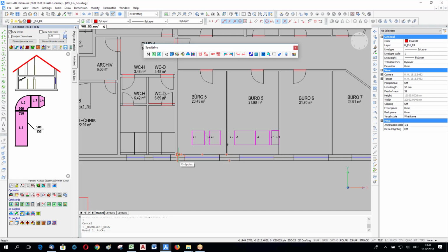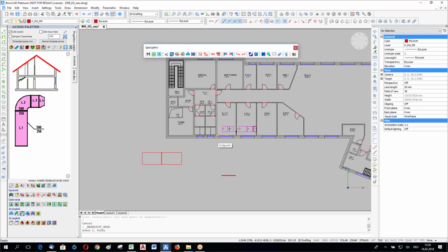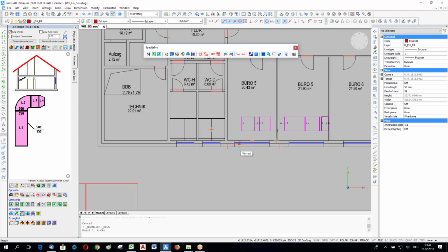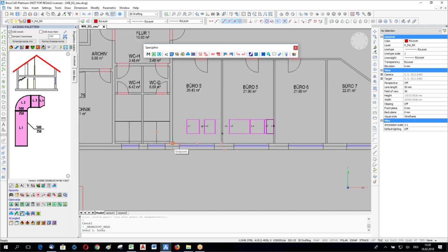The second piece of information is that the software will ask you where the section should be, or where you want to draw the section. I want to have it here in this architect's element, and the first point I selected in the plan view should be on the same position as you select in the section in the second step. So as an example, the first point is at the left side corner of the room. The second point is maybe at the right side of the room. The third point, my orientation I want to look to, is in the room.